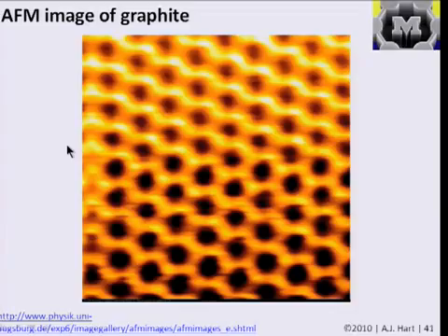So if I have my little pencil and I scan it up above a step, and that step is 1 nanometer high, I can actually measure that height with fairly reasonable certainty. And that's another thing that I might do with an AFM as opposed to an electron microscope.